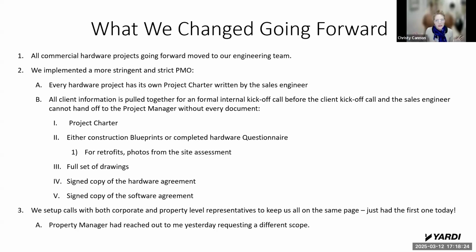For retrofits, always photos of the site assessment, a full set of the engineering drawings that we do that show where we're going to install that equipment, electric panel schedules and which circuits get mapped to which submeters, and signed copies of all agreements. And I didn't put this here, but the proposal as well.